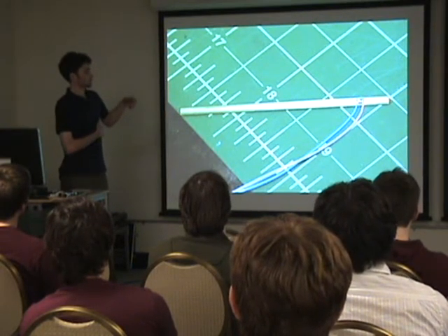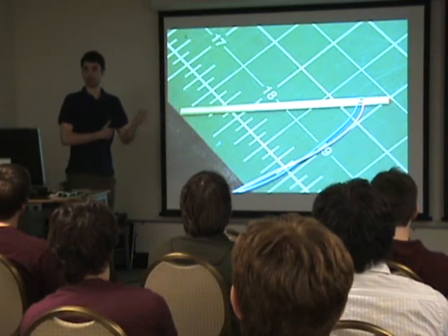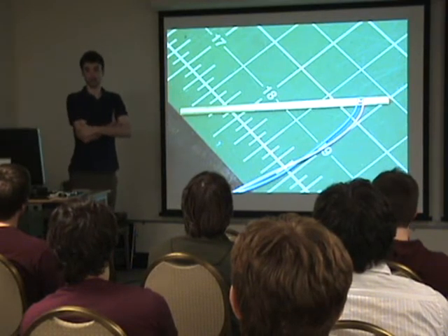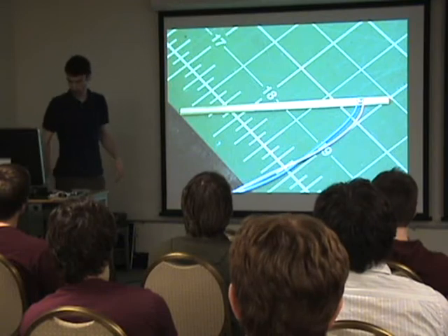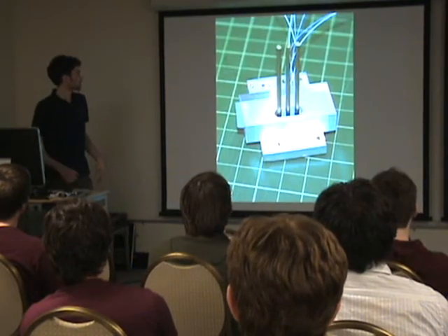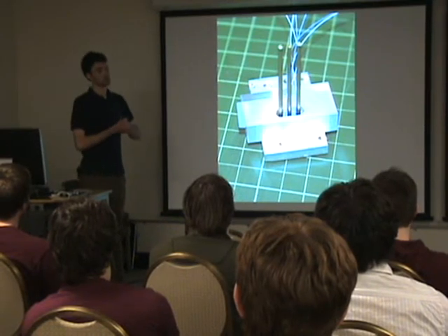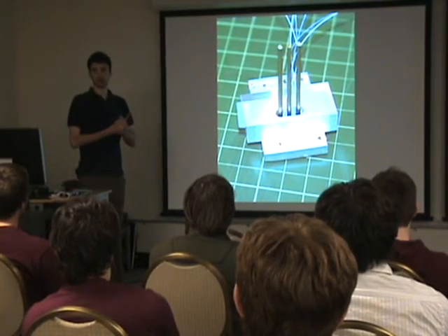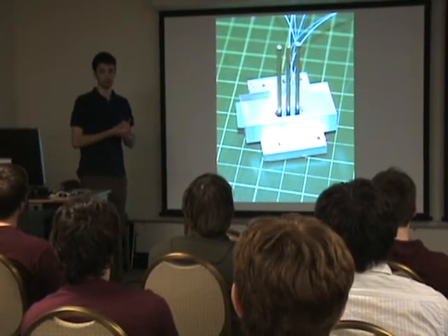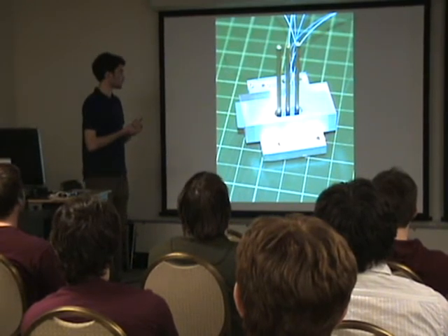I guess the LM35s are actually really nice because they interface with the Arduino without an issue at all, and that'll be part of my project later here. So you can see those pins are assembled and then epoxied in place, and our epoxy is our insulation barrier between each heater pin, each heater element.